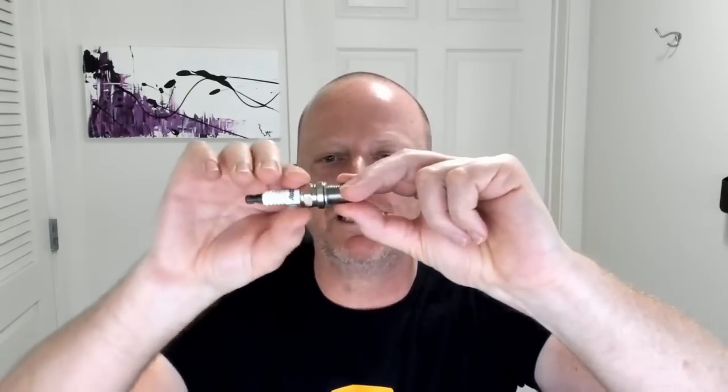What I'm going to do is leave the stock solid all the way to here, where my hand is, so that it's nice and rigid when we're machining. Then after I finish everything in this segment, I'm going to machine a little bit more, and then a little bit more, and then we'll part it off. I'm going to show you guys how to do that.